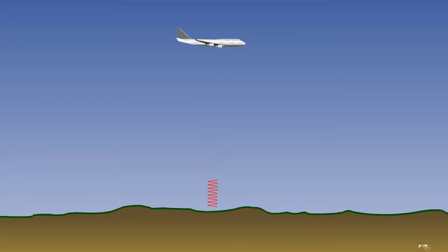Let's see why. There is a limit to how short it is possible to make the pulse while still packing enough energy into it. A typical value for a high-level radar altimeter was a pulse length of 1/4 of a microsecond, that is, 1/4 of 1/1,000,000th of a second. When you multiply that by the speed of radio waves, which is 300 million meters a second, the result is a pulse 75 meters long, or, since we are using it to measure height, about 250 feet long.